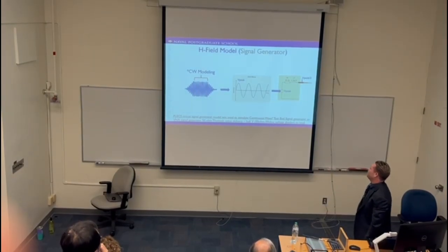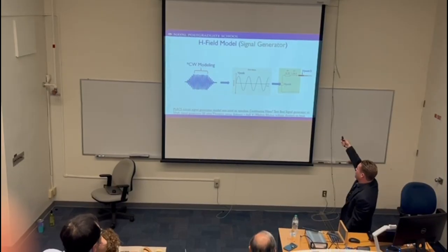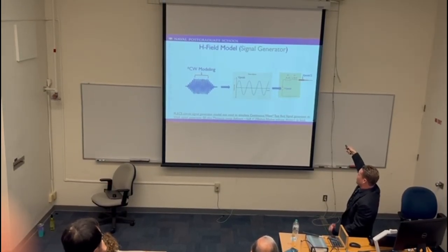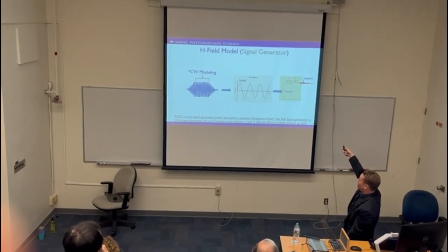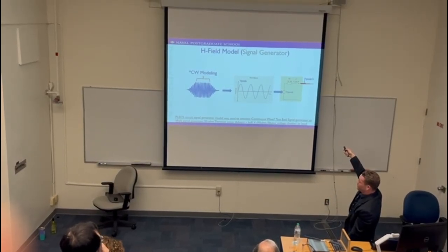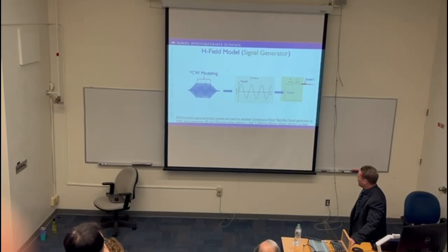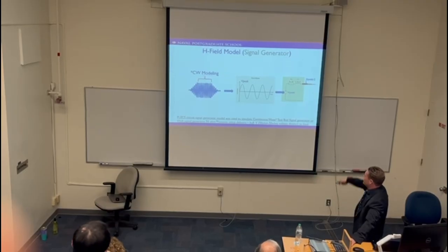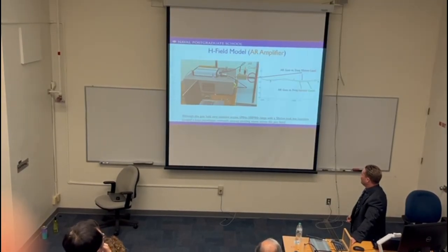And as soon as you put that 50 ohm in there, you notice that you're essentially getting a voltage divider at the output that's feeding into your coaxial cable. So if I'm going to go, say, 900 volts VP, I'm only going to get like 450 volts at the input to my injector. Having that 50 ohm in there and realizing that it's in essence a voltage divider, even with a short at the end of it, was critical in understanding.